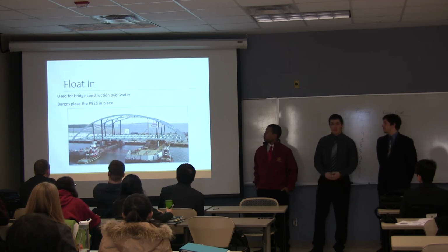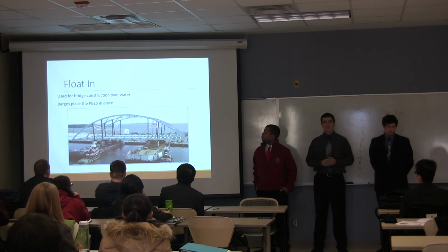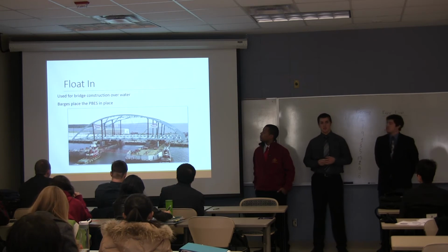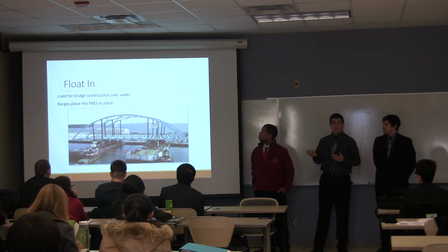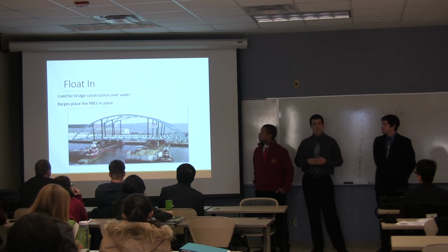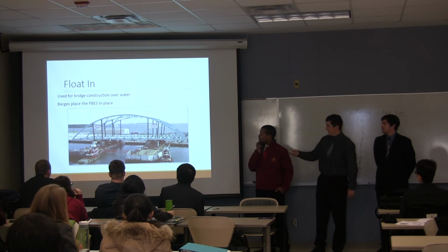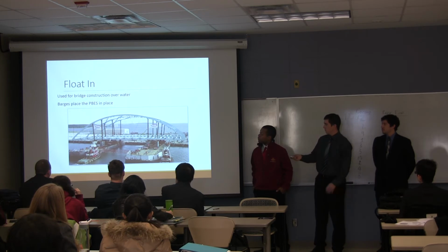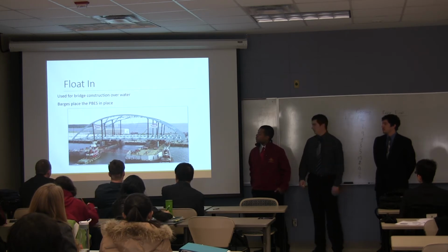And that's a faster way of building those types of bridges. Float-ins are really basically the same thing as lateral slide-ins, only they're over water, so obviously you're going to have to float the bridge in. And here you can see how they have a bridge system here, using barges to place it into place.